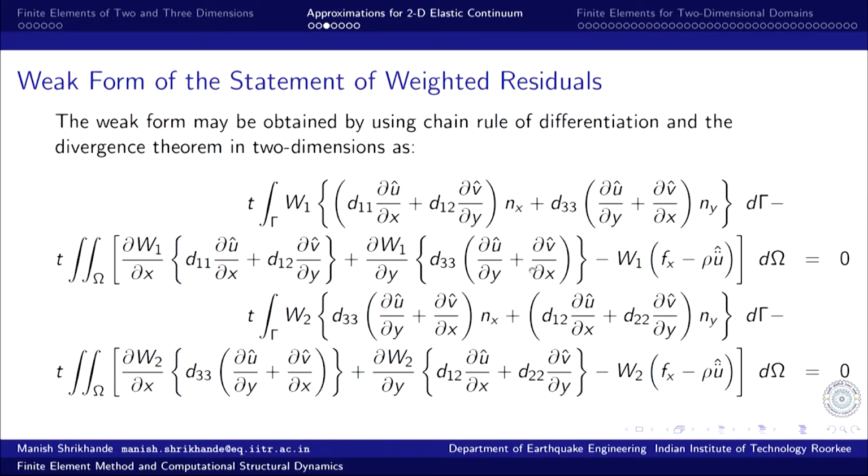So, we are done with this. Now, we need to look at what is the body force component. What are the nodal equivalents of these? If you look at it, this is essentially the work done, work equivalent. The work done by these forces in moving through the displacement should be the same as the work done by the nodal forces we are putting in the nodes, in moving through the nodal displacements, the primary variable of that node. That is what is evaluated.